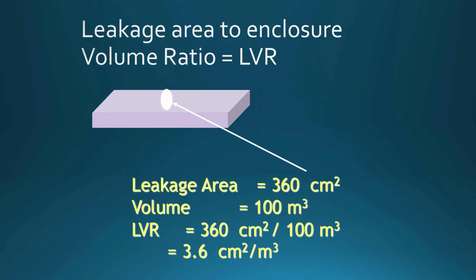The other problem with peak flow rates is that there is still the guess as to what happens when these various peak flow rates go into an enclosure, and it's always been assumed that the enclosure responds in a square root function. It's not a square root function at all. It's about a 0.9 function. So that was one of the first discoveries that we made.